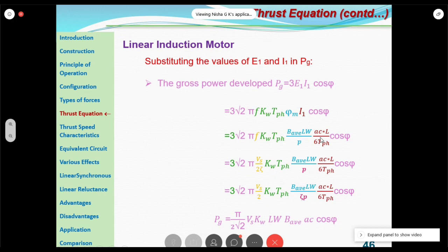What you have to do is divide this by the slip S. You get the parameters, but you have to refer them to the primary side or the secondary side. Here we are referring to the primary side. So you will get R1, X1, R2 dash, X2 dash, and one more parameter, R2 by S. If you add and subtract R2, you get two factors, R2 dash and R2 dash into (1 minus S) by S. This is a fictitious representation. Here there are two powers: one depends on R2 by S, and the other on R2 dash into (1 minus S) by S.